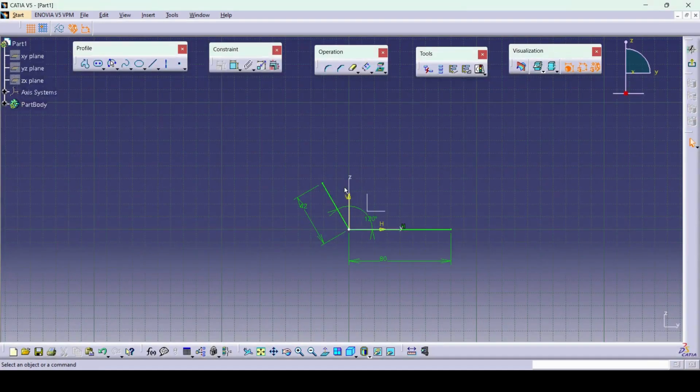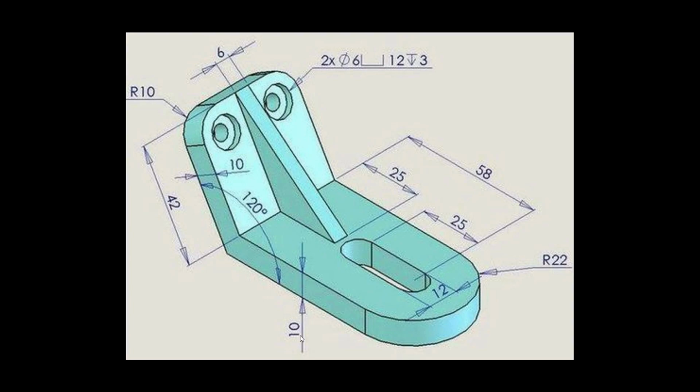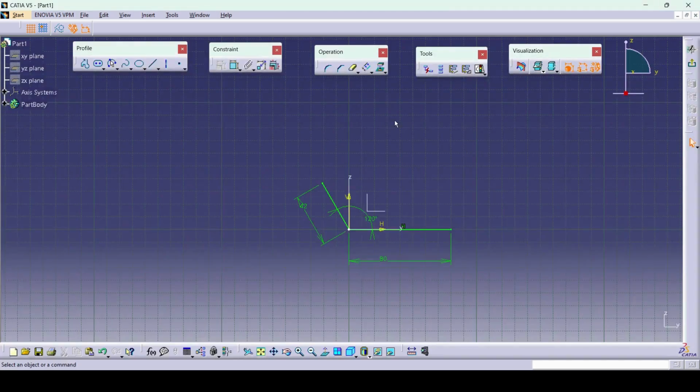The same profile you need one more, with a height of 10 mm. So for that you can directly use the option called offset. Then here we need to turn on point propagation. It means whatever elements we have with relation of point, all elements we are able to offset at a time like this. Then to specify the offset dimension, you can use Tab. As you can see, upside we will jump into offset. We need a dimension of 10 mm.